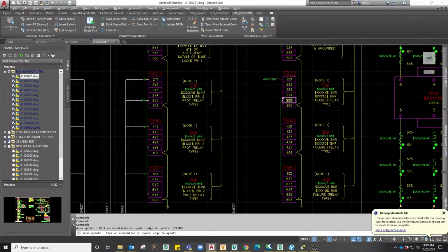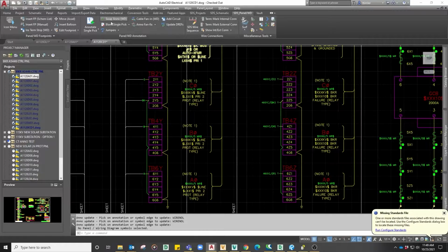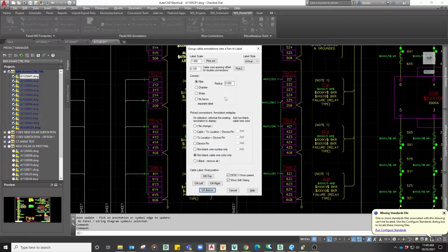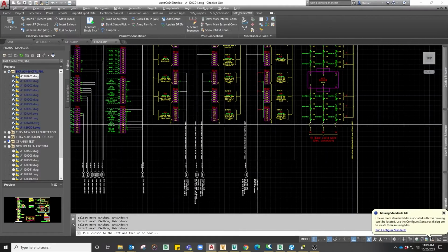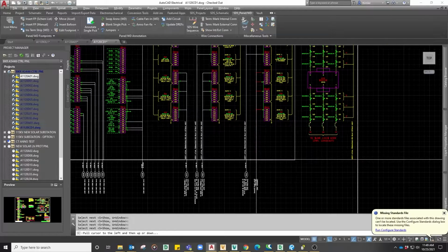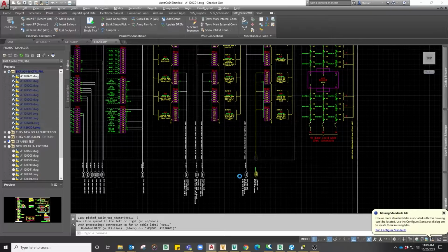Then I'll select Annotate Single Pick, keep the defaults, and select the single terminals to annotate the cable. Next will be to select the WD cable tool to draw out the cable. I'll keep the defaults and click OK Bottom because I'm landing this cable at the bottom of the drawing. Select each annotation individually and just find a good place to make that first pick, and then draw the cable bubble out to be aligned with the other stenciled cables.